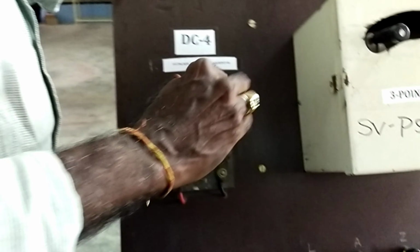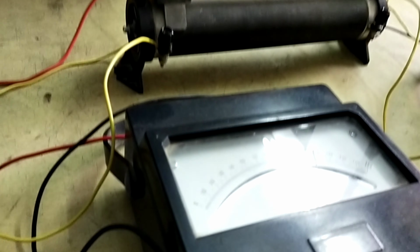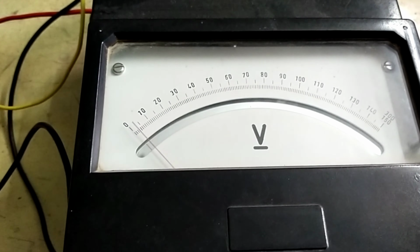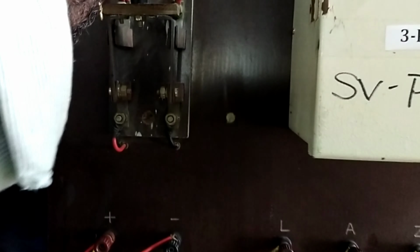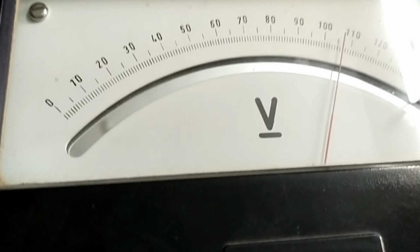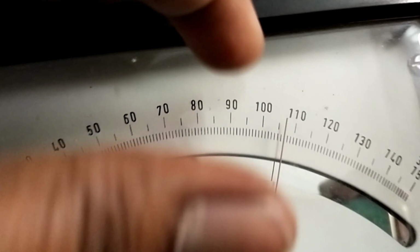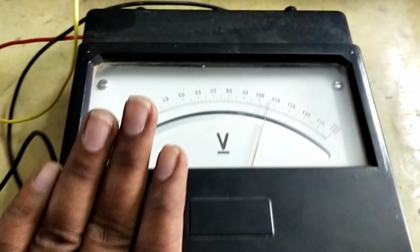Now we switched on the supply. Now the voltmeter. Now the voltage is 0. If you switch on the DPST switch, the voltmeter shows some 110 volts into 2, hence we obtain 220 volts is given to the 3-point starter.